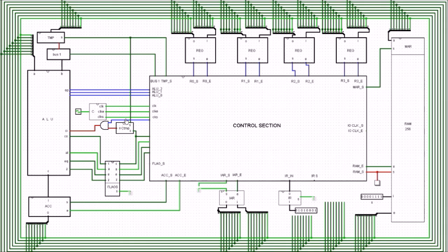So whenever this goes high, it tells us that we're at the right point of the ALU instruction, and at that point we can look at the carry in and we can use the carry in. But otherwise, we won't be interested in the carry in, and that carry in will be low. So it means that we don't have the potential of adding an extra 1 on whenever we do the fetch cycle. So that's one problem, but we run into a second problem as well, and that's what this little register's for.